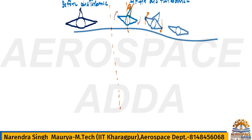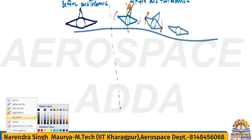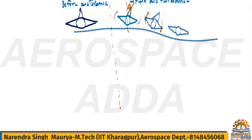Anyway, if this airplane is laterally stable, then, in what direction is the moment acting? In this direction the moment is acting. Once disturbance came, then the moment is acting like this. So this side wing is going down and this side wing going up, that is rolling. So this moment is the applied moment because of the disturbance.